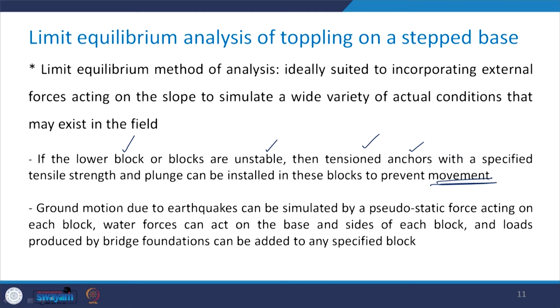In case of ground motion due to earthquake, that also can be simulated by a pseudostatic force acting on each block. Then water forces can also act on the base and the side of each block, and the loads which are produced by bridge foundations can also be added to any specified blocks.